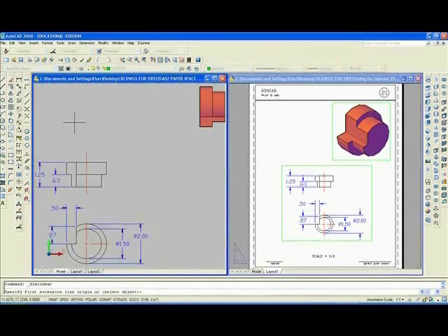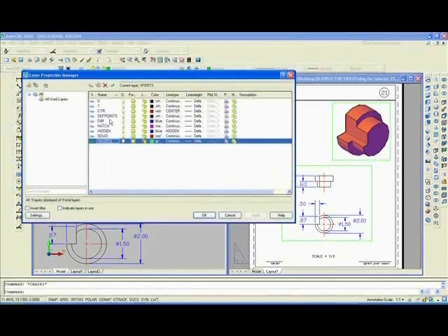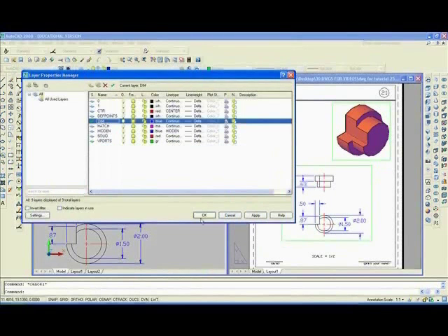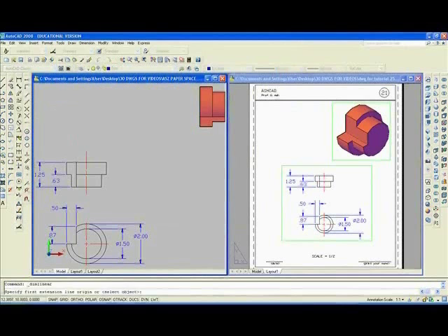And I'll just put any old dimension here. No, I guess I have to type D-I-M-S-C-A-L-E, dim scale 2. I'll pick any dimension like that. No, I should be on layer, dimension, current, and I can put a dimension anywhere like this. That's how big it should be, and I could use the paintbrush to match it.